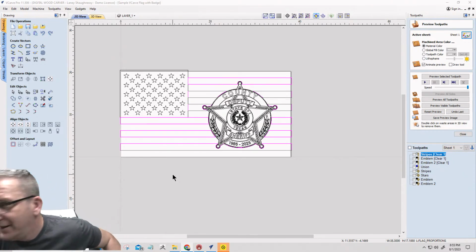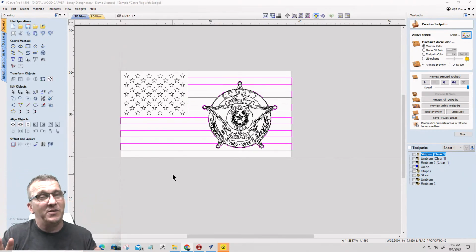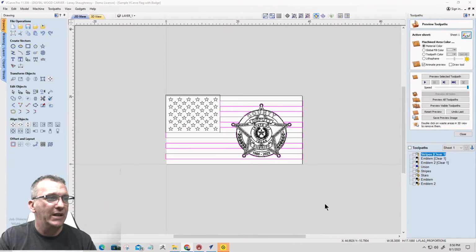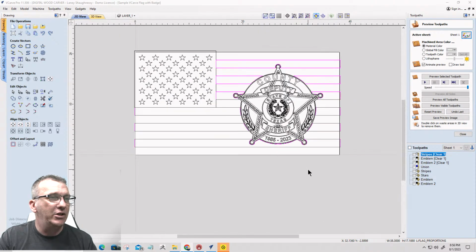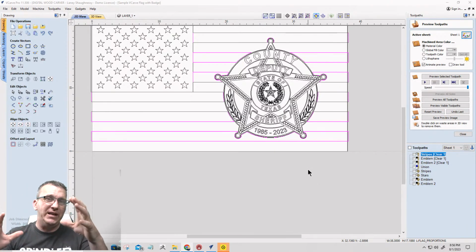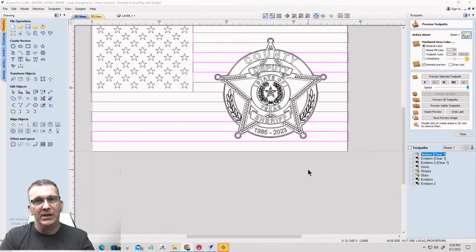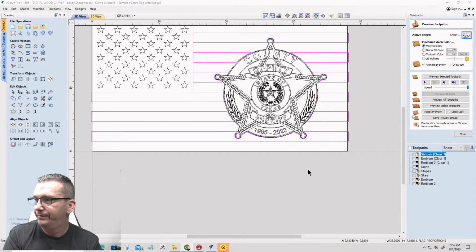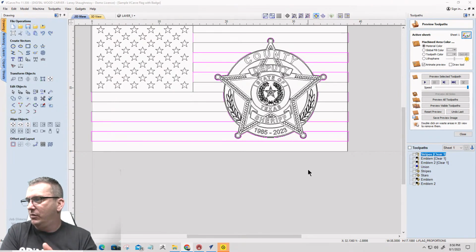All right. That's the discussion on speeds and feeds, guys. That's it. We're going to move on now. 18,000 RPMs is good for everybody. That's your starting point. Slow down as that bit gets bigger. Slow down as that bit gets smaller. You know, your feed rates and all. Listen. It's audible. Listen to your machine when it's carving. Listen to that bit and adjust accordingly. That's it. All right, you're welcome, Sylvia.